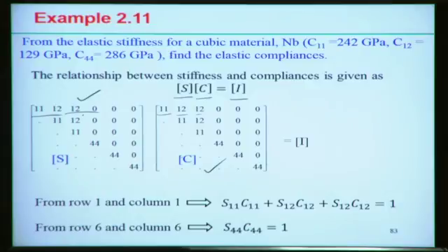Okay. Now first, because of cubic symmetry, only three constant terms are required: C11, C12 and C44. So basically, if we find at least three equations, then we can solve them and find all these things. But tactfully, we need to consider this relation like that. Here I is basically 1, 1, 1, 1, 1, 1 on the diagonal and the other terms are 0.